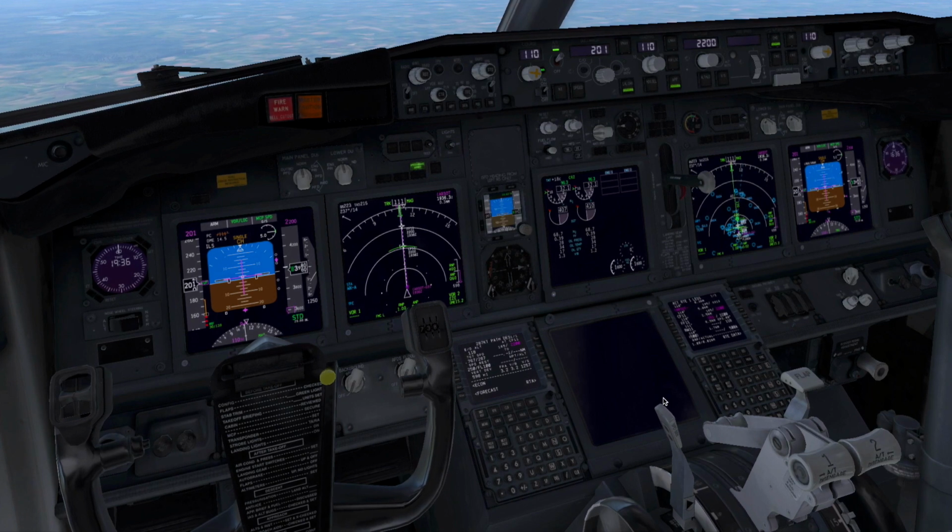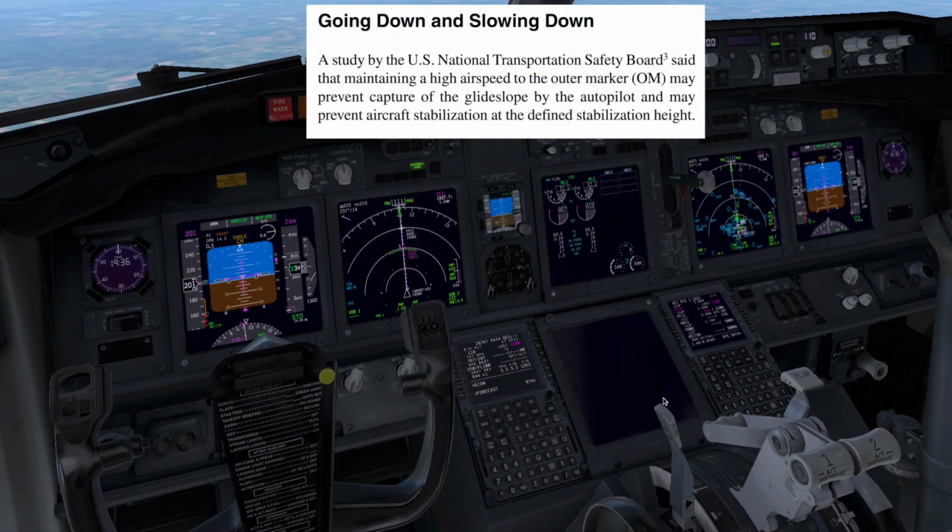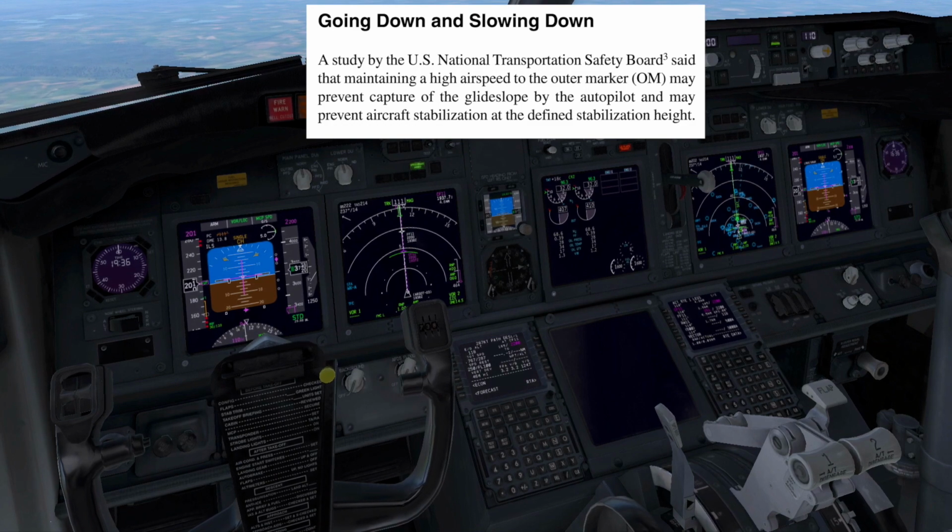Now we're getting closer to the final approach fix, so it's a good time to start extending the flaps. Let's go for flaps 1 and command the speed for flaps 1.